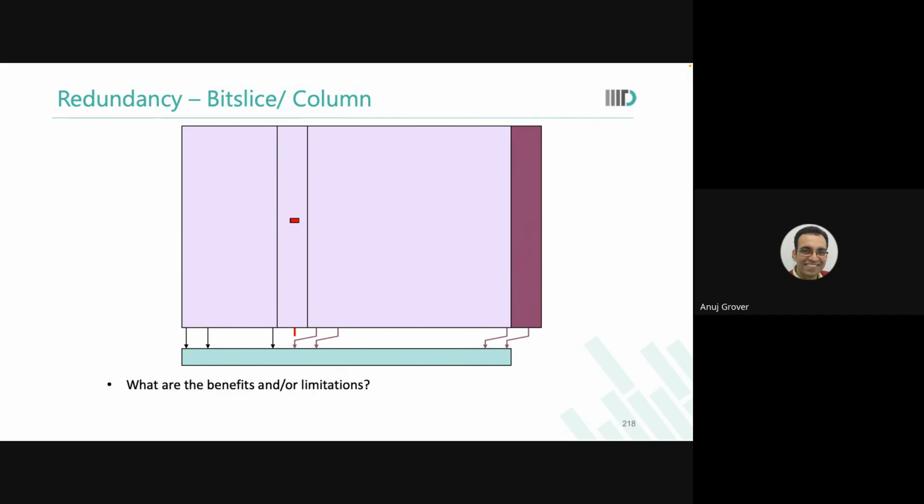Arey, this is a basic electronics question. What is the logic that we are applying? Yes, you will need comparators on the columns. What will they compare? I tell you that column number 158 is failing, and you have to tell me whether you have to shift or not shift. So what kind of a comparator do you need now? You have 1000 columns in your memory. I have told you one column, number 158, is failing. So you just need the equality comparator, right?